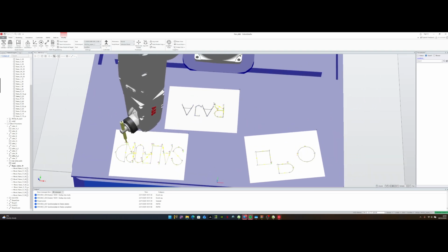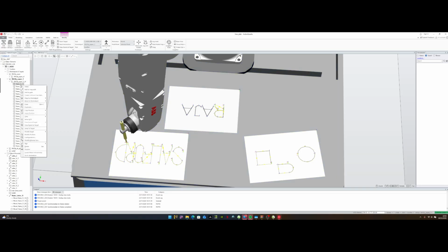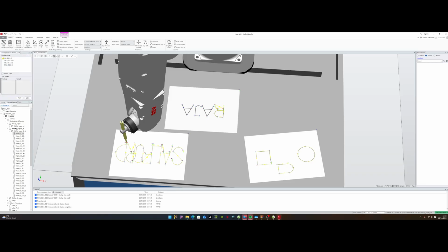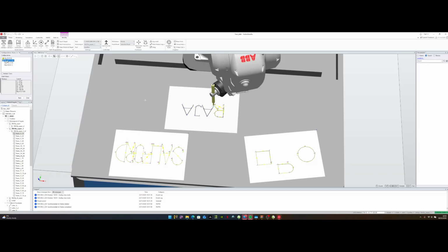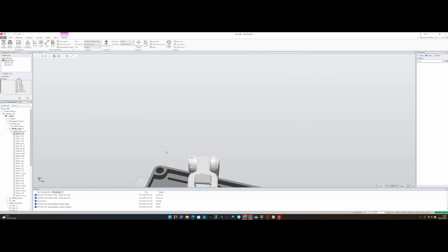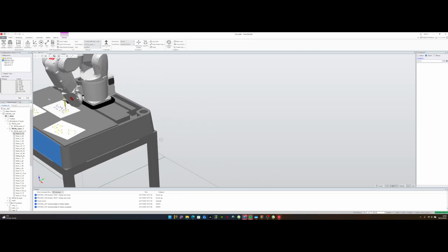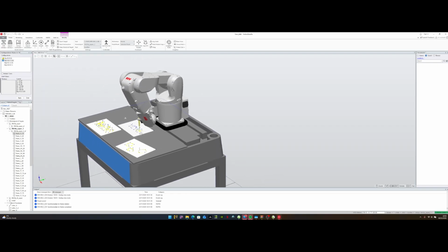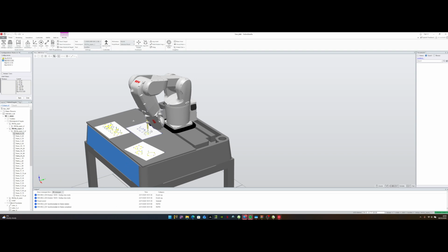Yeah, okay. So essentially, if I'm not mistaken, you have to click and modify the configuration. Some configurations might not work, like this one doesn't work. This one does work, and I can go over there and take a look at what the robot looks like. So this is what the robot looks like. This is part of the reason why initially I wanted the letters up a little bit, to make it easy for the robot to reach. So this configuration works, this one works, this one works as well. I like this one, so I'm going to use this configuration.